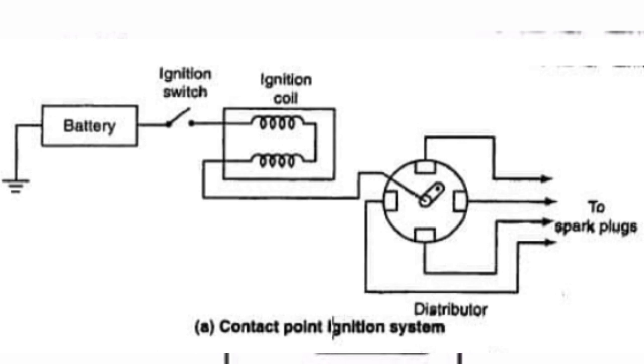Contact points. The contact points, also called breaker points, act like spring-loaded electrical switches in the distributor. Their function is to cause intermittent current flow in the primary circuit, thus causing the magnetic field in the coil to build up and collapse when it reaches maximum strength. Wires from the condenser and ignition coil primary circuit connect to the points.